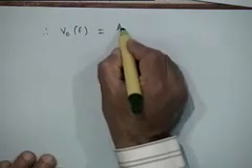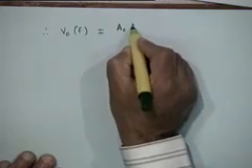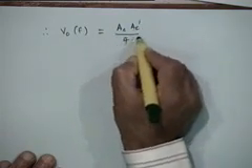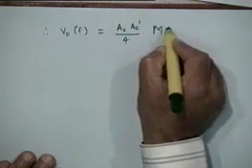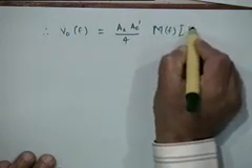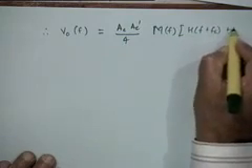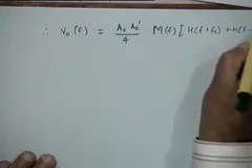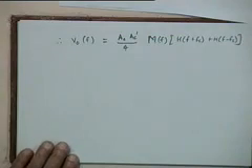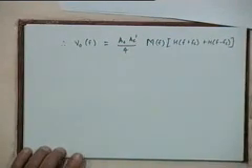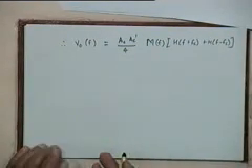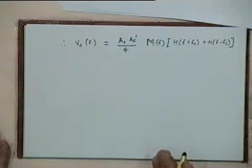So you will get an output which is AC prime upon 4 into M of F into H of F plus FC plus H of F minus FC, right? That's what you will get, and that provides the answer we are looking for, right?